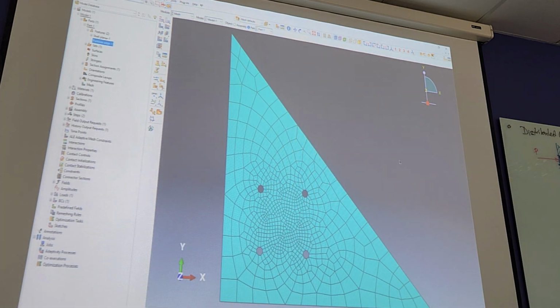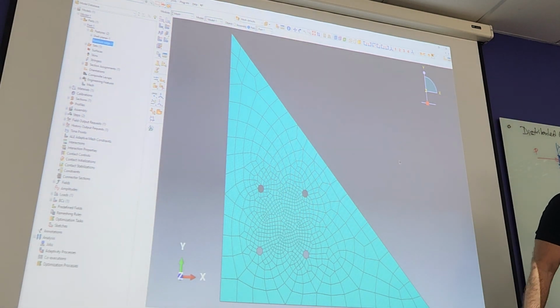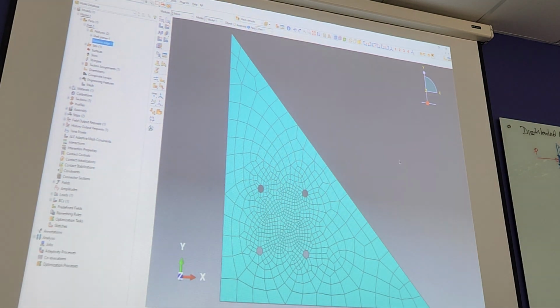When we talked about regions of interest, this bit here is also a so-called region of interest because that's basically where the load is applied. Right? So you want to make sure that you have enough elements in connectivity so the load is transferred over here. Yeah? So let us go and do some of those changes and potentially improve the mesh.